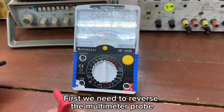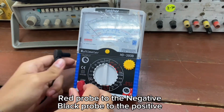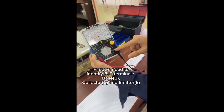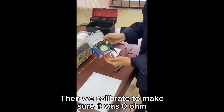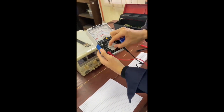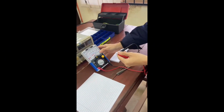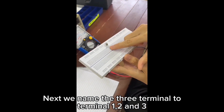First, we need to reverse the multimeter probe. Red probe to the negative and black probe to the positive. Next, select the ohm range to 10 to 100 ohm on the multimeter. Then we calibrate to make sure it was 0 ohm. Next, we name the three terminals: terminal 1, 2, and 3.